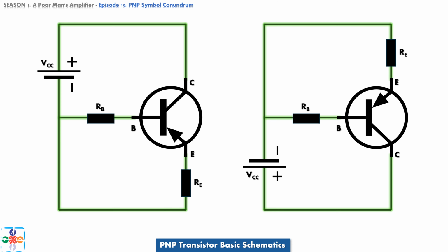It would be prudent to abandon looking for symmetries between schematics for PNP and NPN transistors. They can be very confusing and misleading. Although they have similarities, it would be very prudent to distinguish between them, and treat them as separate components, because they are. The primary reason for varying the orientation is to get clearer and more readable schematics. Engineers and designers will orient the symbol to minimize crossing lines and simplify the overall flow of the circuit diagram. So, this is all just for aesthetics.